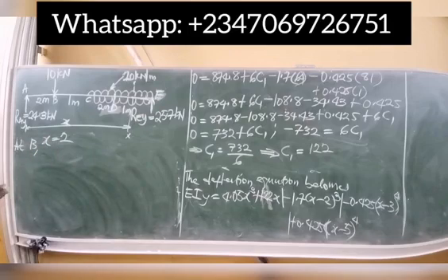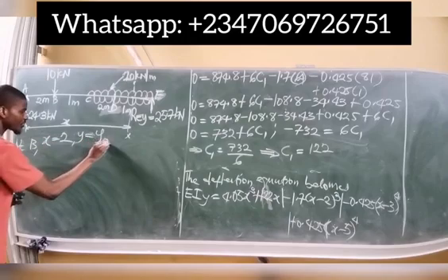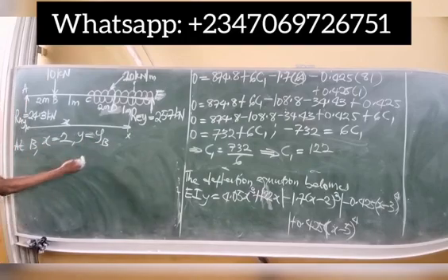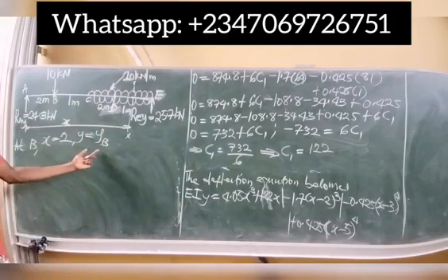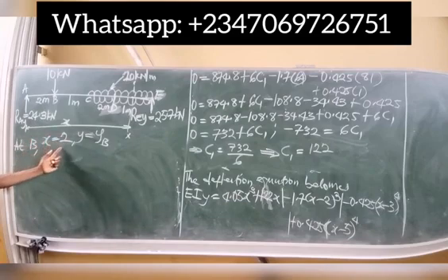2, and deflection at that point is simply called YB, which means deflection at B. So for this value of deflection, we'll simply replace it with YB, which is deflection at point B, while x is replaced with 2 meters. So we can find that deflection.